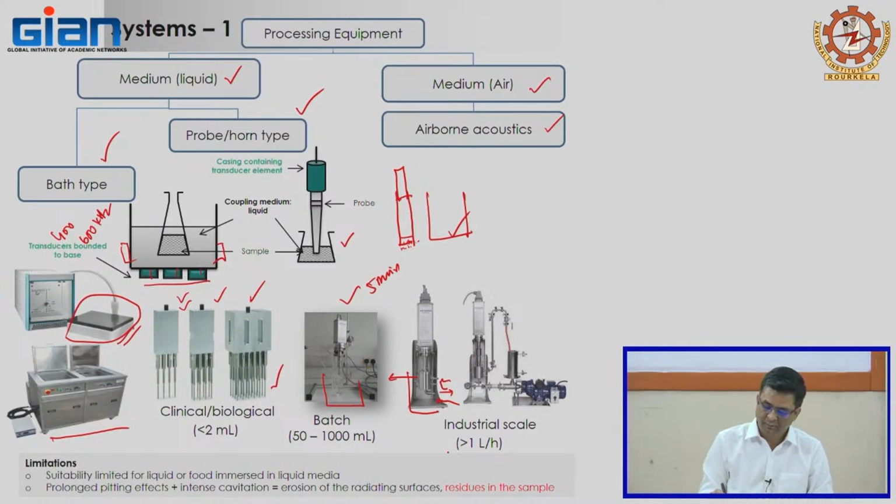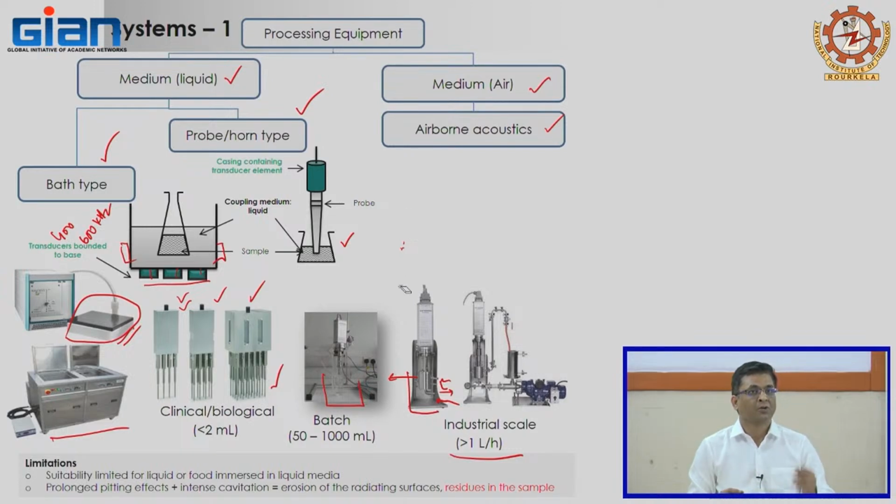Now if you see here, suitability is limited to liquid or food immersed in liquid medium, because you need to have a liquid there. And one question comes all the time: if we are using ultrasonic all the time, the pitting, that means leaching of material, comes into the liquid food. We carried out that experiment extensively and spoiled almost 10 to 15 different types of probe to see the amount of metal which leaches.